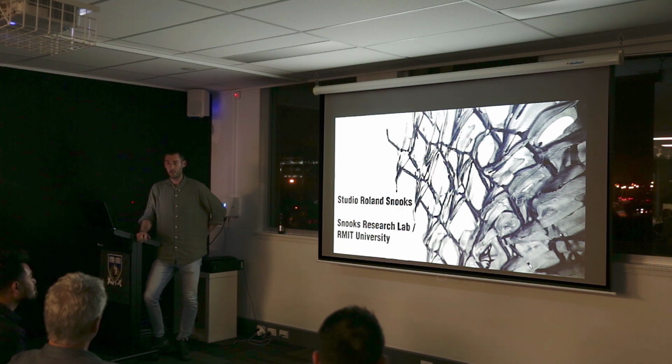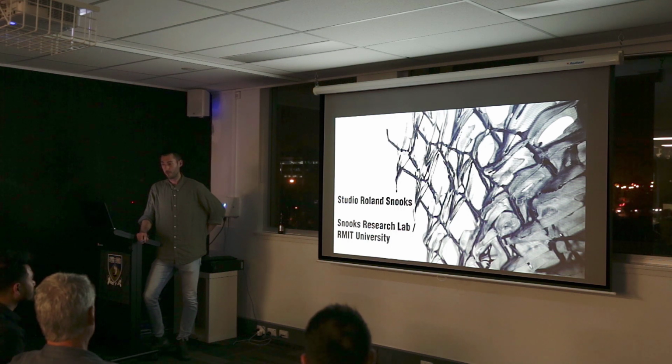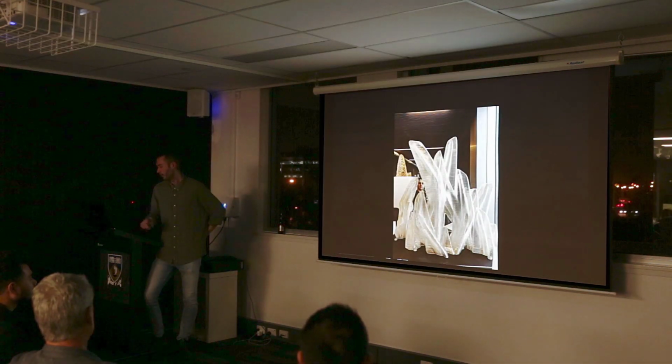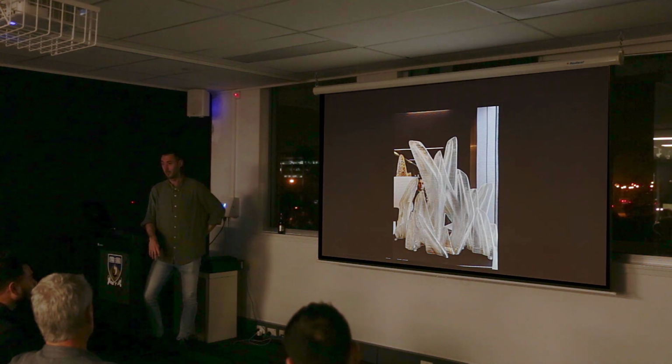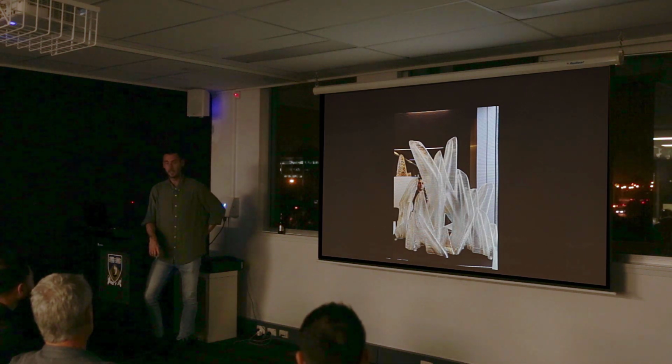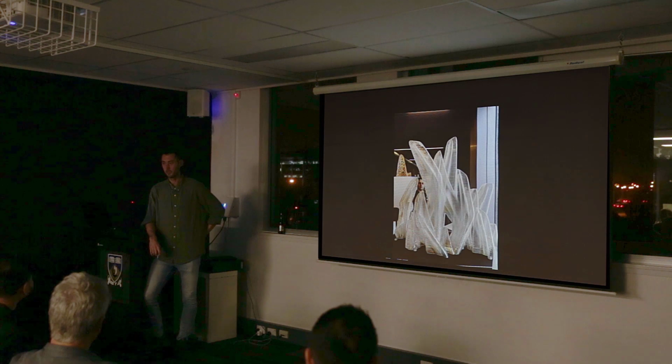And the other problem that we have is that we're printing on a print bed that is only 700 by 1400 millimeters wide. So we can't print this thing in a single piece at the moment. You can see that they're all individual parts that are going to have to be joined together, which means there's going to be a lot of opportunity for point loads on this thing, which it's just not going to handle. It's also cantilevering out about 3 meters above people's heads, so there's a huge amount of pressure on those joints.